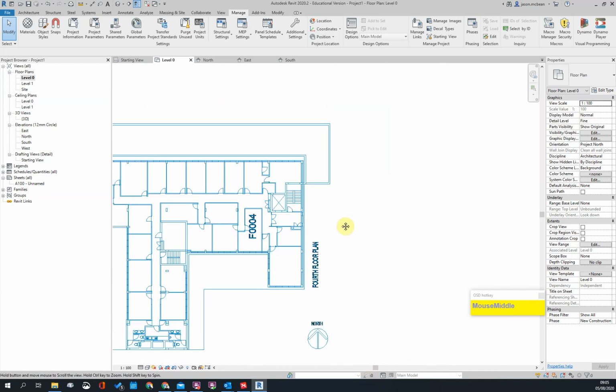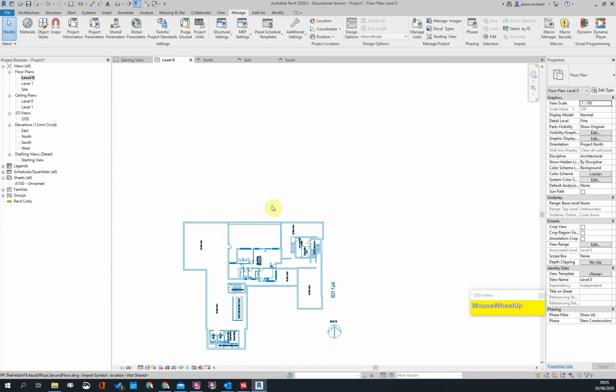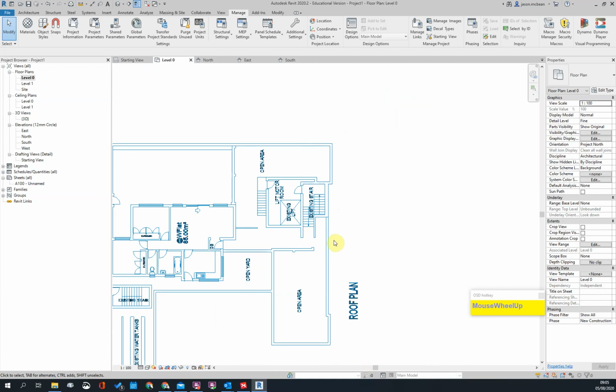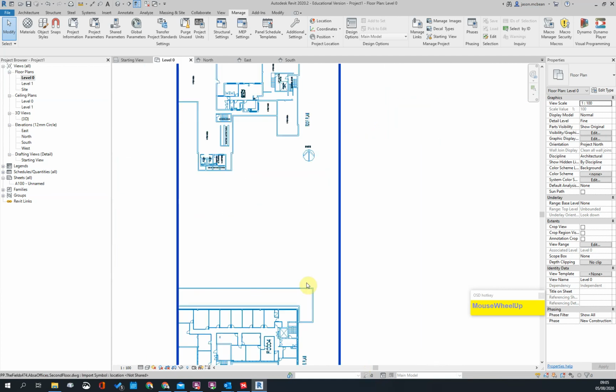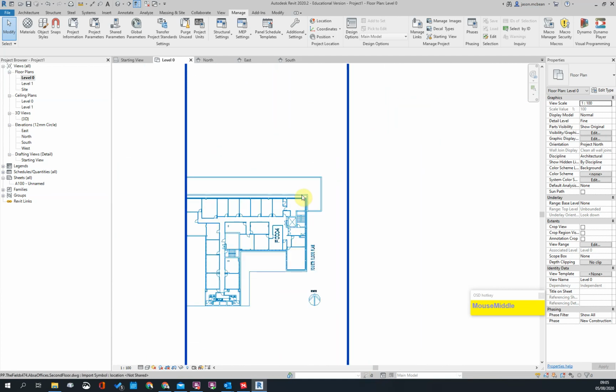So we've got 4 floors and a roof, and then probably another little level somewhere over the lift, for example, because a lift typically has a pit, which is like a little basement that it goes into, because the lift's mechanism needs to run up and down, and then it has an overrun. So once it's reached this top level, it'll have another story in which the lift will need to overrun by, and there's a motor above the lift to basically lift the lift up and down.